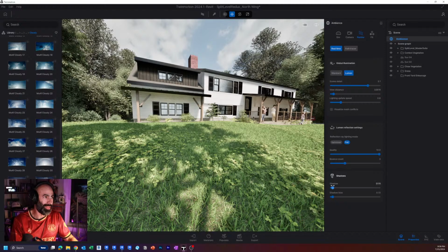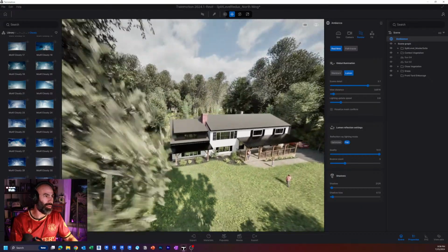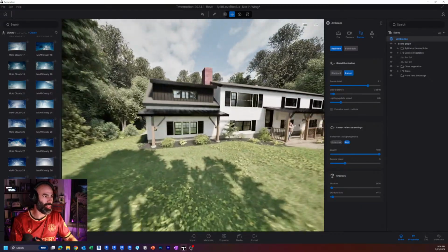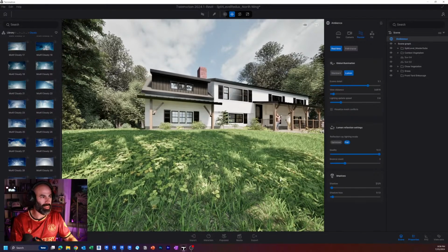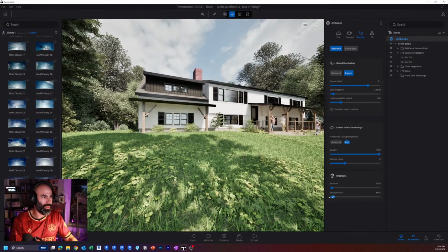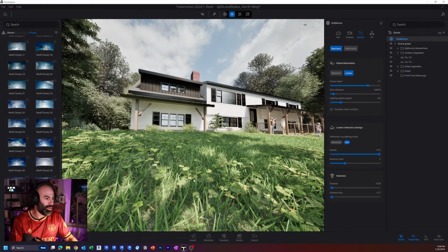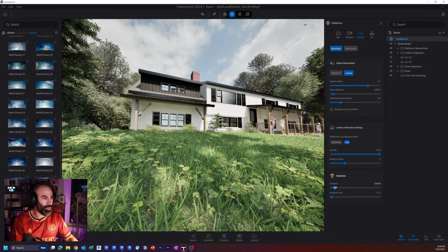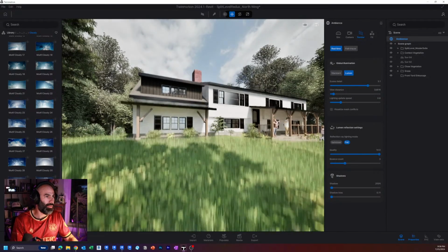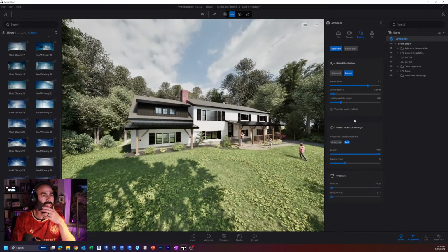it is important that you find a happy medium between too far and too close. Basically what I usually do is I'll either measure in Revit or sometimes even Twinmotion what the deepest shadow I need is, and I'll go with that. So you can see here if I do 200 feet and then I play with the shadow bias a little bit, notice these clovers in front are starting to look really realistic. That's how you kind of know that you're getting what you need. Again, if I slide this from 200 to 1,000 feet, notice how different the front shadows look. So I'm going to go back to 200 here. So that's your shadow bias.